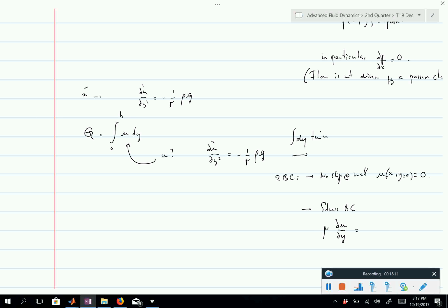If you had a water-oil interface or an oil-something else interface where the two fluids are viscous, you may have to match the two tangential stresses, because you may still have to solve for the velocity distribution in the other phase. But in that case, what is on the other side of the paint is air, and air is going to exert very little tangential friction onto the interface.